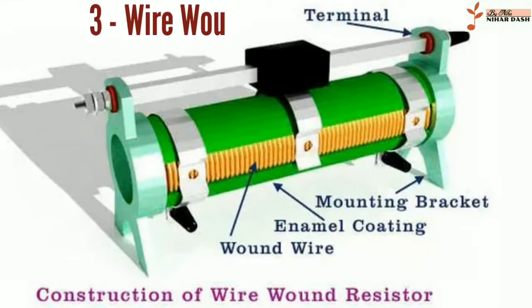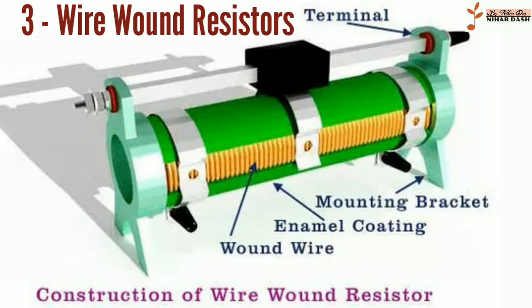Wire-wound resistors. High-power wire-wound resistors are used for dynamic braking on an electric railway car. Such resistors may dissipate many kilowatts for an extended length of time. Types of windings in wire resistors. Common on a thin former, wire-wound resistors are commonly made by winding a metal wire, usually nichrome, around a ceramic, plastic, or fiberglass core. The ends of the wire are soldered or welded to two caps or rings attached to the ends of the core.